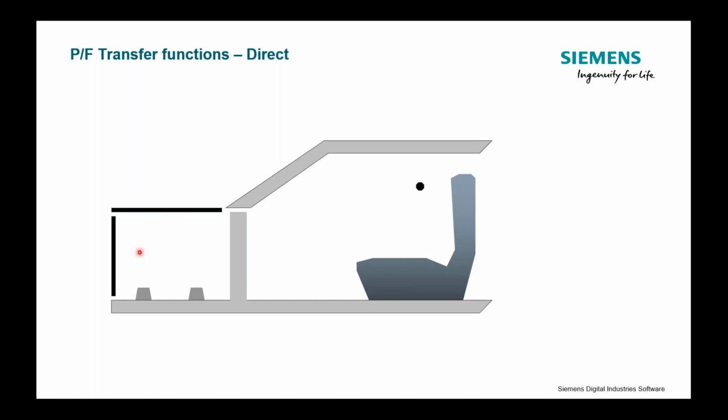We want to know how much engine noise gets to our driver's ear through the engine mounts. So I've got some P, that's my target or my receiver, if you will, the driver's ear pressure microphone. And we're going to make some impact measurements at the two engine mount locations. In this case, I've got a simplified vehicle with two engine mounts.